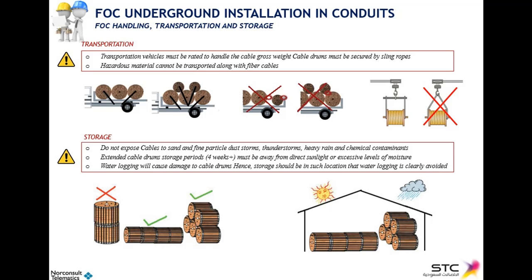Regards cable drums transportation, you can see on the top left corner of your slide the proper ways to transport them. All drums must be tightly tied to the truck. Do not transport drums that are loose, moving away inside the truck. This is strictly forbidden. It's a risk for cables and people.